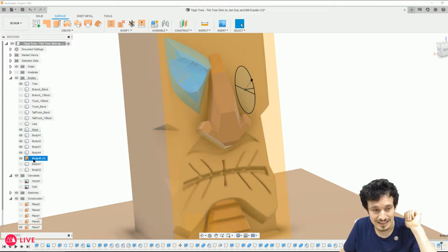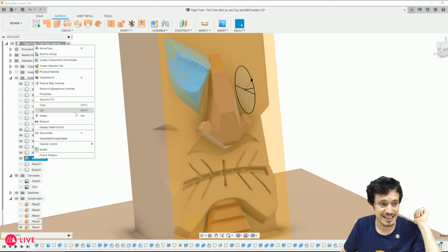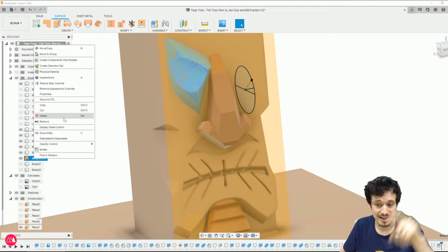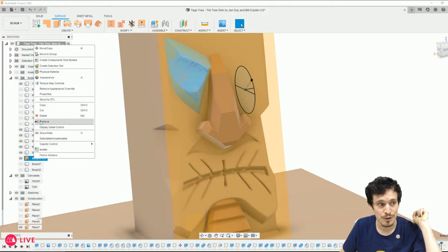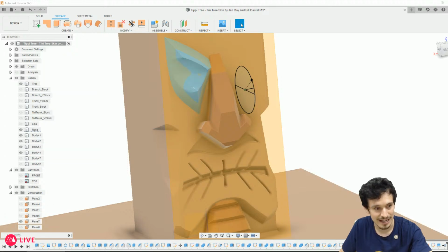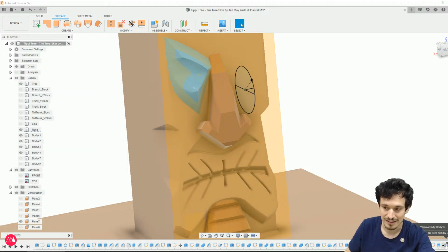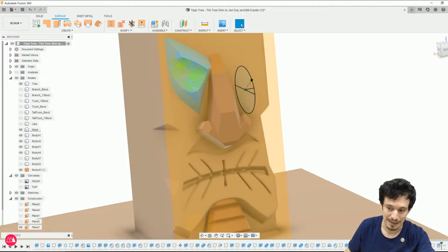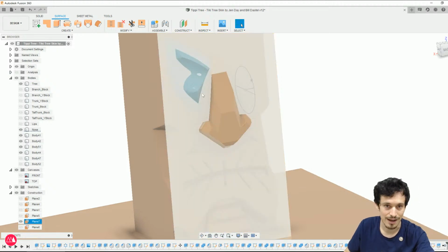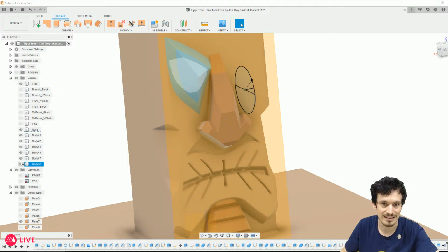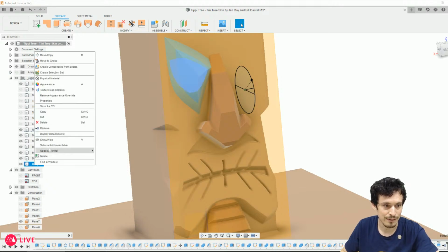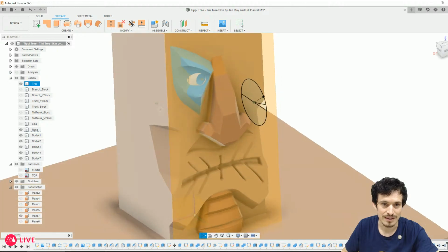Maybe I shouldn't take the risk. See, if you delete something, it'll also destroy anything that you've done in the past with your project that uses that part. But on the other hand, you can use the remove tool, which removes it at this point in your design on the timeline. So there's an actual remove there. It still exists earlier in the timeline, but once you get here, it's gone. That's the safer way to remove things. We can do that with this part as well.